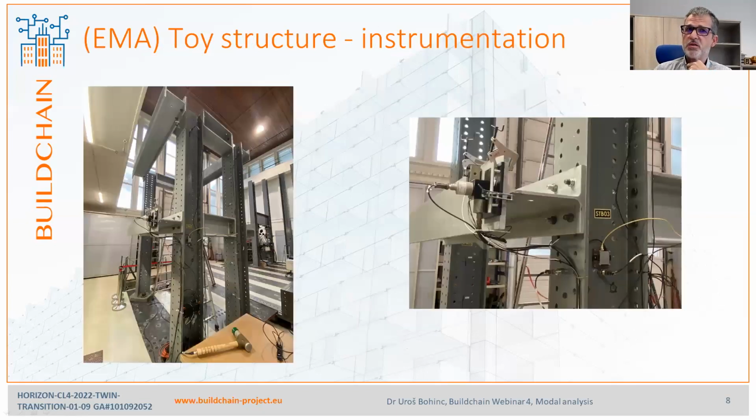So I will now present two cases where we used both methods. The first one is where we applied the experimental modal analysis using the impact modal hammer to excite the structure shown here. This is like a toy structure built in our structural testing lab. This is a very simple steel structure, but still not trivial.